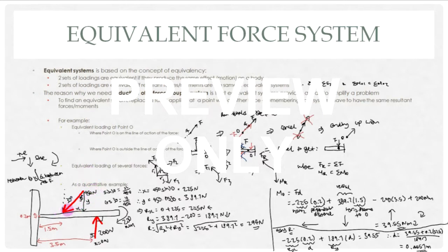You've got the red line going down there, and that's 30 degrees, which effectively means that it's 30 degrees there because it's an alternate angle. And then you've got this one, which is just going up there with 200 newtons. This one's 450 newtons. Now, first of all, you've got to understand, basically, we want to shift this one down to the origin, and we want to shift this one to the origin as well. We can find what x is then for that one.